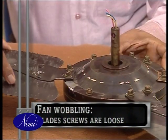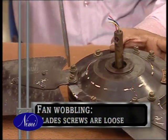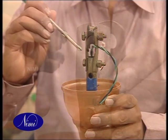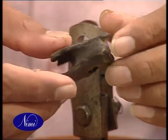The fan might wobble if the screws which attach the blade flanges to the motor hub are loose. Also check for the tightness of the bolt and nut in the shackle and hanger clamp. Check the grommet for damage. Replace if necessary. Next, let's see how a ceiling fan is to be dismantled.